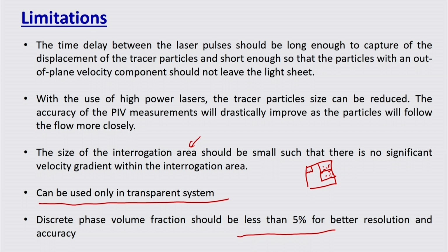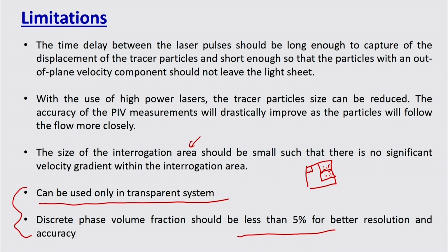What we discussed till now is about the optical based techniques, which are LDA and PIV. I have also touched upon PTV, which is particle tracking velocimetry. These are all optical based techniques, and the major limitation of each is that you need a transparent wall, and you need a transparent system too. Once I say transparent system, it means the fraction of the discrete phase should be very small.